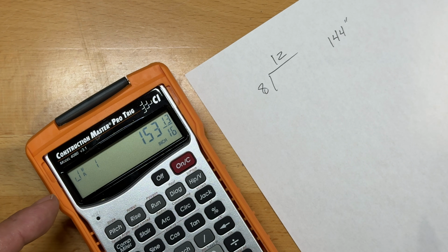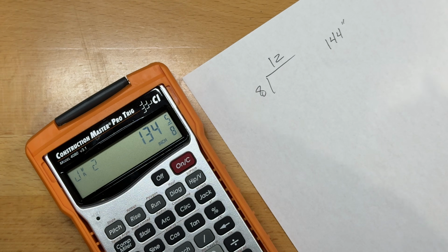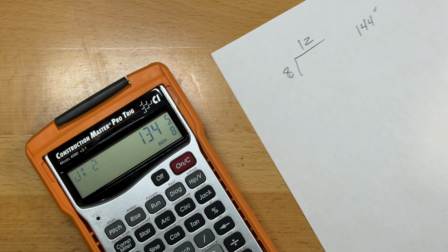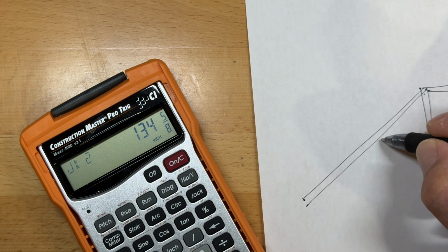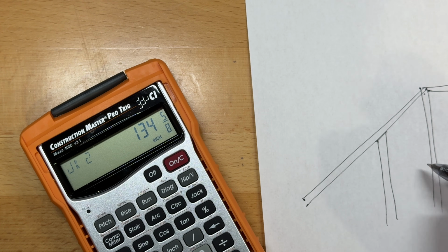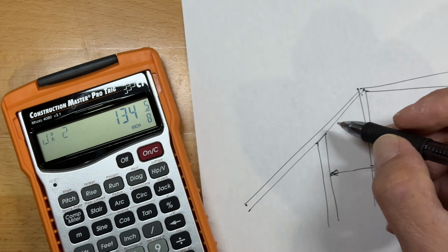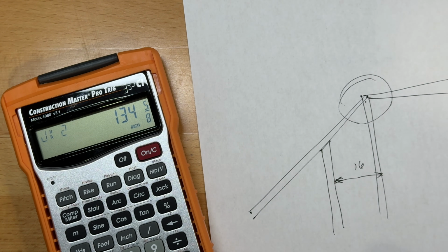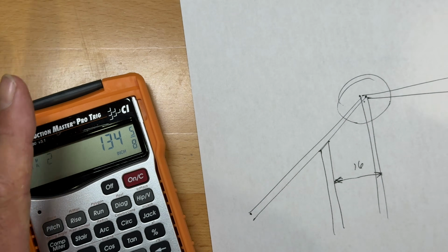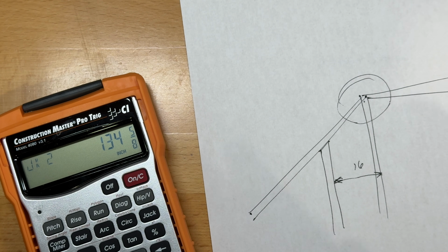Now, because the first jack rafter is wrong, all the spacing for all the other jack rafters is also going to be wrong. So if we had a 45-degree hip here, and we'll just try to do a quick drawing of this, your jack rafter is going to have a cheek cut of 45 degrees. Now, the measurement between here and here, you'll usually measure to the long side of your jack, is going to be 16 inches. But the problem is right up here, and I'm going to blow this up, and I'm going to show you exactly why the calculator gets this wrong. Why, I don't know why it doesn't figure it in, but I'm going to show you why the calculator gets this wrong and how to correct it.